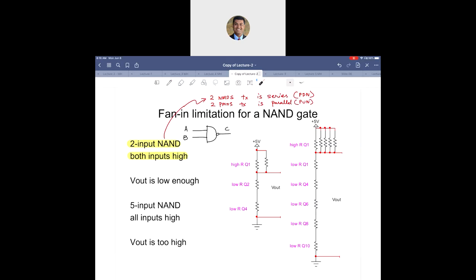If I treat the transistors as simple resistors, which can have a resistance very low or very high, indicating a closed switch for low resistance and an open switch for a high resistance, then I'm just modeling those as the resistor symbol. So that's my two-input NAND gate: two NMOS transistors in series in the pull-down network, and two PMOS transistors in parallel in the pull-up network.